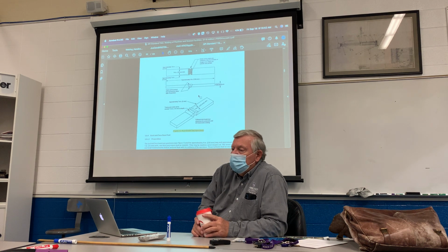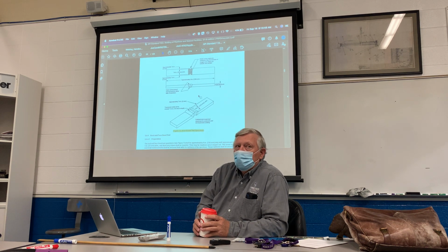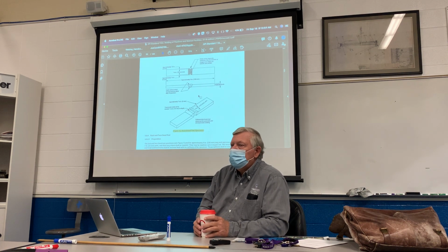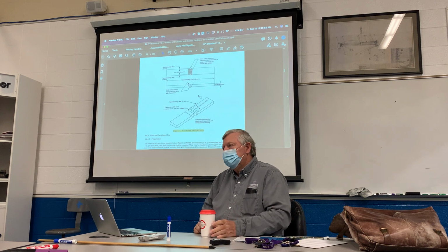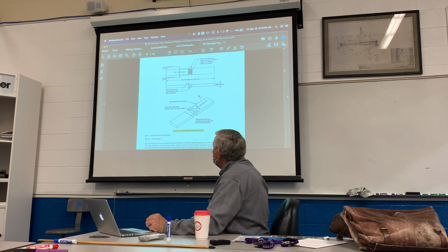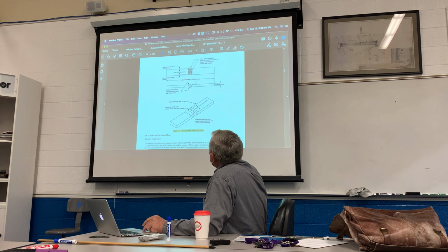To the untrained eye, it's really kind of a hard test to determine anything from. Because mostly if they've welded it right, with the right heat, and they've got adequate fusion, and they've cleaned things out, then the nick breaks will be clean. But here's the problem. It shows approximately 3/4 of an inch, and then they're supposed to notch out by hacksaw.